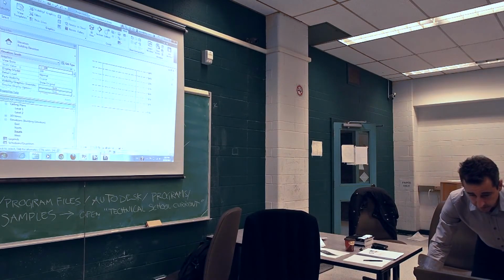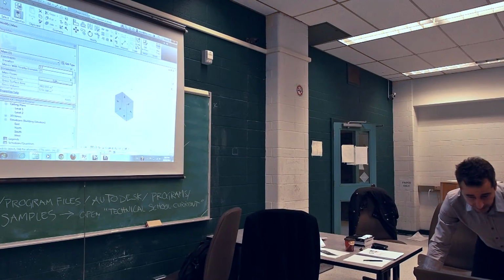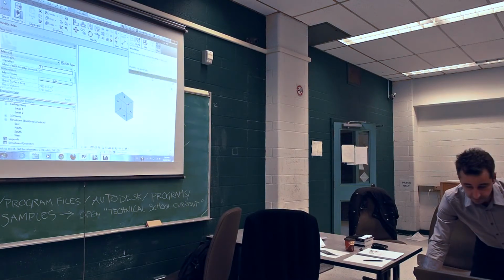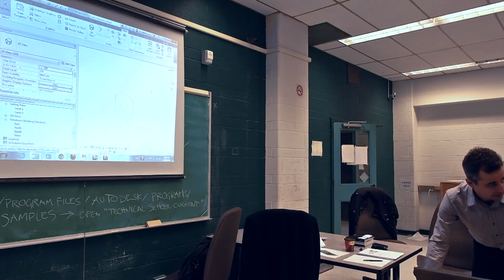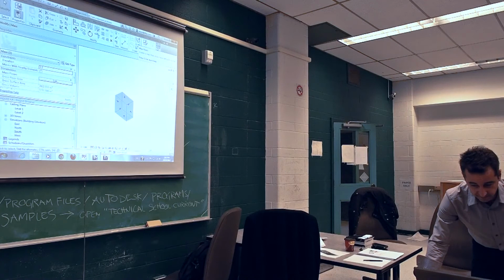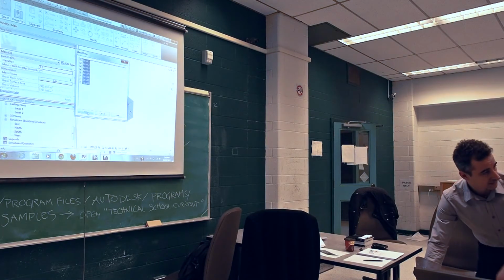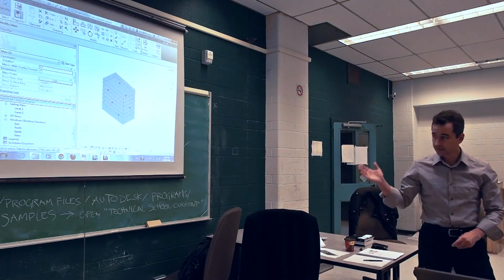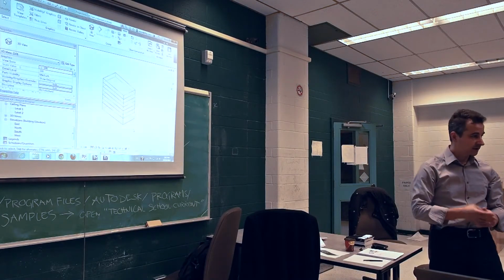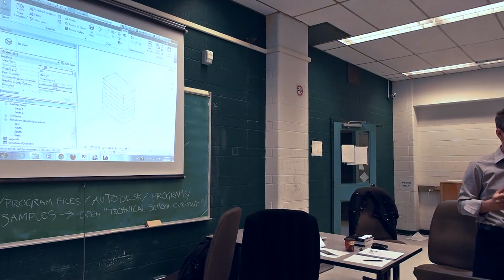So again, in my 3D view, I will select my mask, and I have this contextual menu. Again, contextual menu is something that you don't see unless you have something selected, right? So if I get out of the selection, it's not there. If I select my mask, I have mask floors. And if I say mask floors, I can select where I want these mask floors. I want them on every single level, right? So I check every single one and say, okay, at this point, my 3D object is sliced at each level, and I start creating, they act like floors.